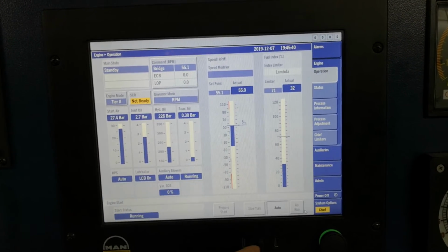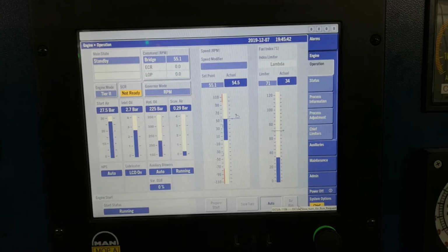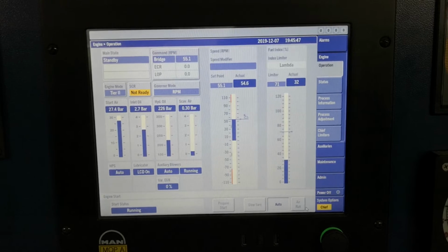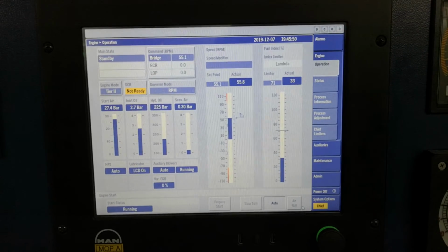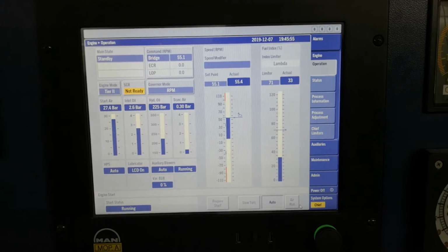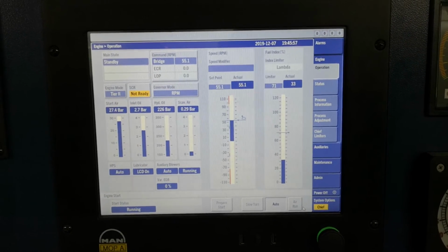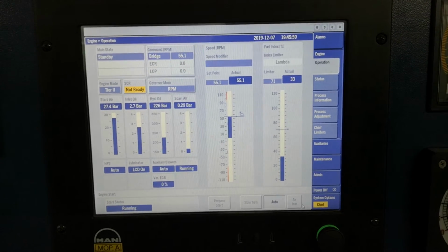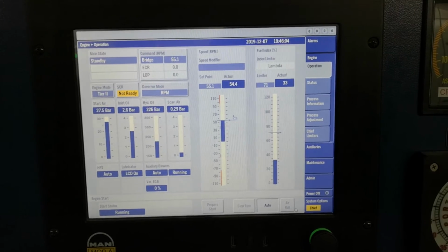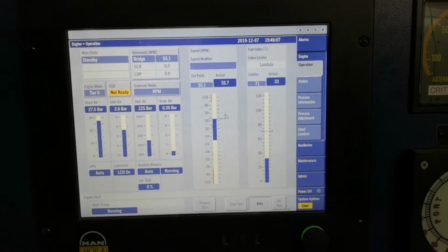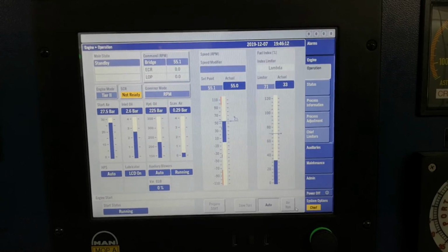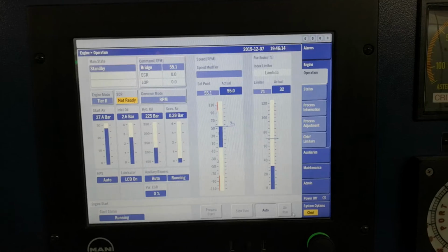And then here, when you stop the engine for 30 minutes, if you try to start, at that time the slow turn is automatically activated. So you have stopped more than 3 times and then try to start, but suddenly it asks why it does not start. Wait, we have the slow turn. Sometimes people are embarrassed, what happened? Why does it not start? So slow turn is activating. And then prepare.